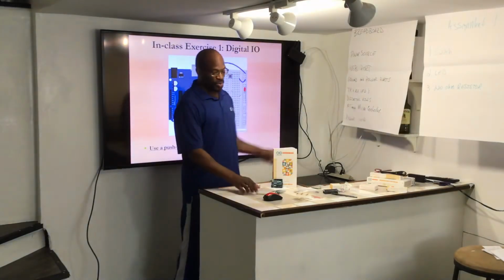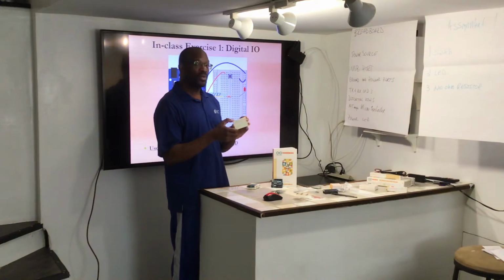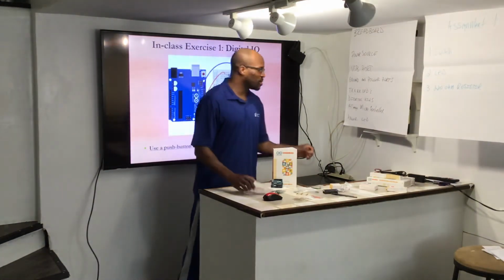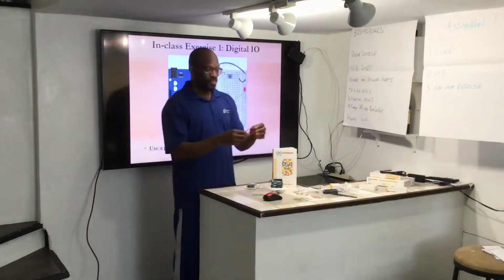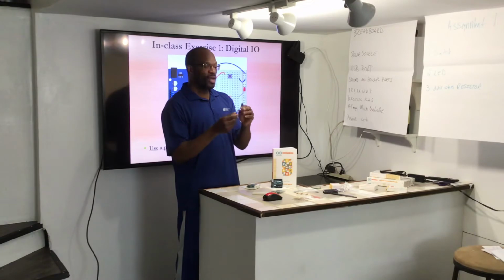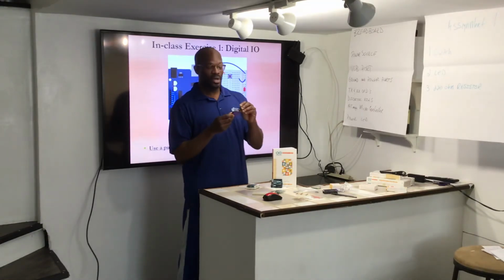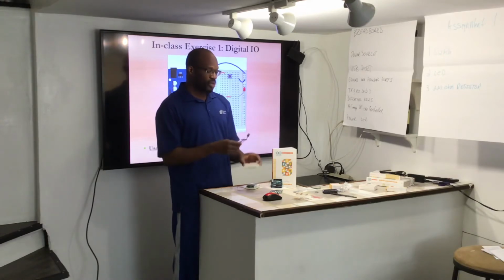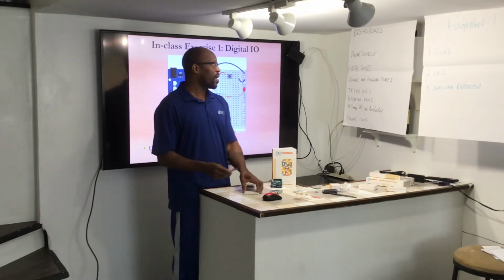for the components that we do have, we have the breadboard, which is going to be our base for connecting our components. We're going to have a power source. These red and black cables are for power and ground. This power source is going to be plugged into a 9-volt battery, which will power up the Arduino and cause our components to work properly.